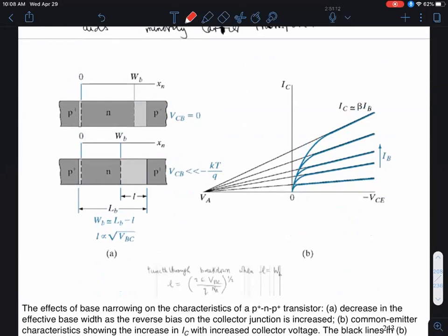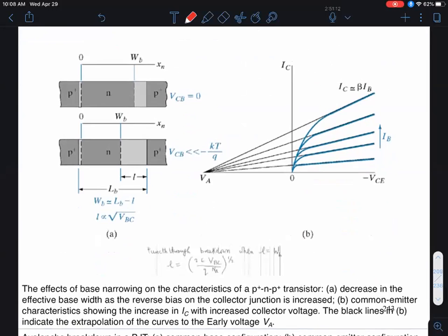Switching gears, another second order effect that you see in a BJT is what happens with increasing collector base reverse bias. So as shown by this lightly shaded region, that's a depletion region at the collector base reverse bias junction. As I increase my collector base reverse bias, or in other words, as I increase output voltage VCE, this depletion region is expanding more and more into the neutral base region, right? Under those conditions, then, the